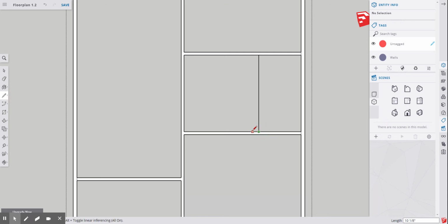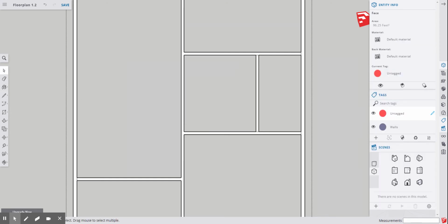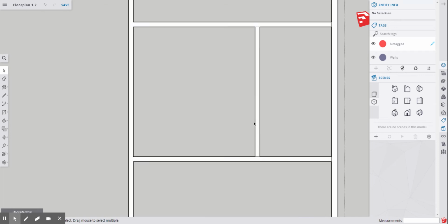From this point over was our wall thickness, and our wall thickness was 4.5 inches. Enter. And delete that surface again. Grab the pencil and take it all the way over. Delete the surface again, and that's the surface I actually wanted. Okay?